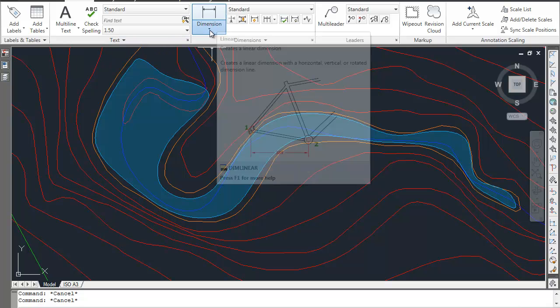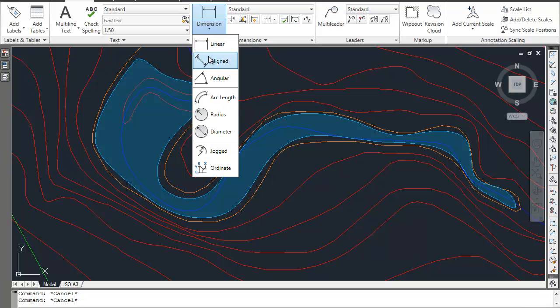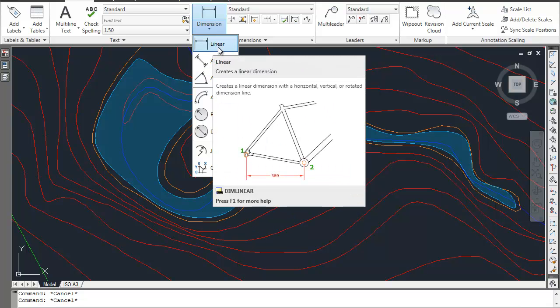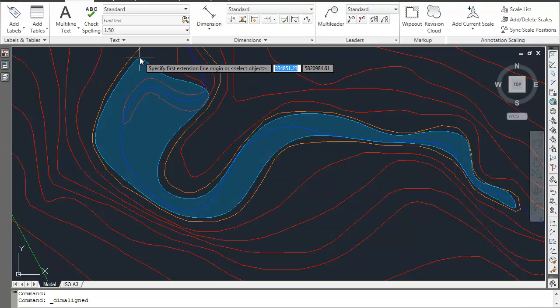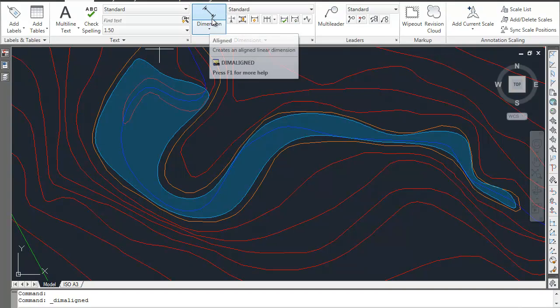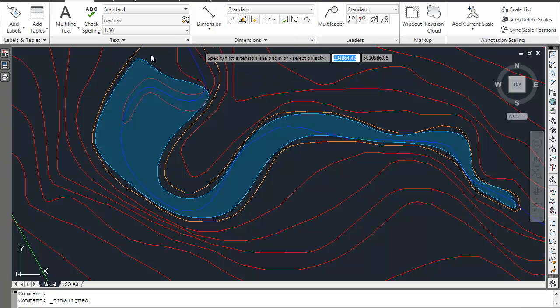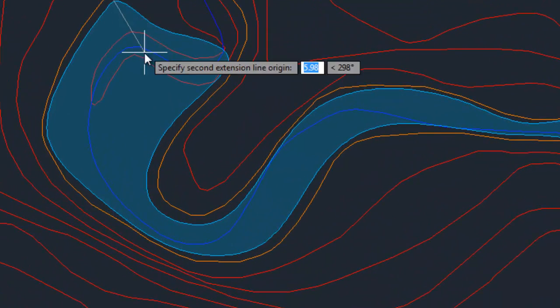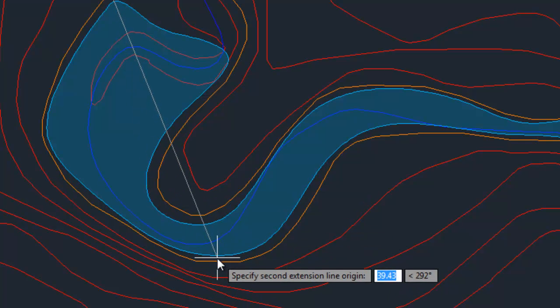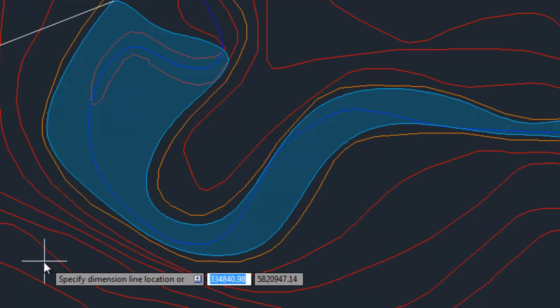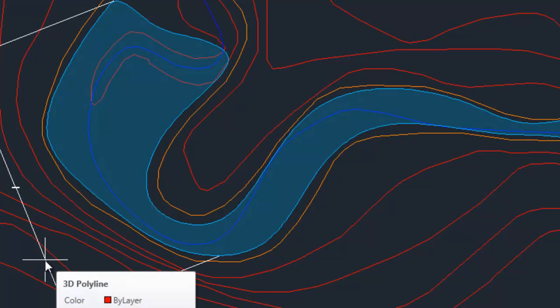Now there's a few different ways of using these dimensions. For this at the moment, I'm going to do this angled one, and I wanted to show you that one for a reason, and then we're actually going to be using this one, which is the linear one, for our settings. When we select our dimension, it will draw it on the angle in which we are drawing this measurement. So when we click here and drag it out, you'll notice the angle is there, and it measures the exact distance between point A and point B.